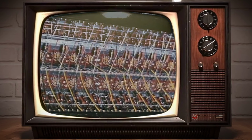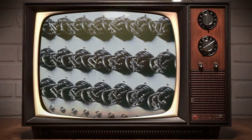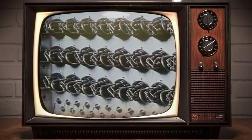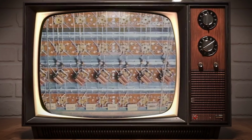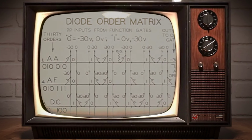Instructions are transferred from the memory to the top or control register of the arithmetic unit. Orders and addresses are separated in a set of function circuits, and orders are sent to a diode matrix for interpretation, while addresses go to the memory control circuits for consultation of the specified spots in the array.